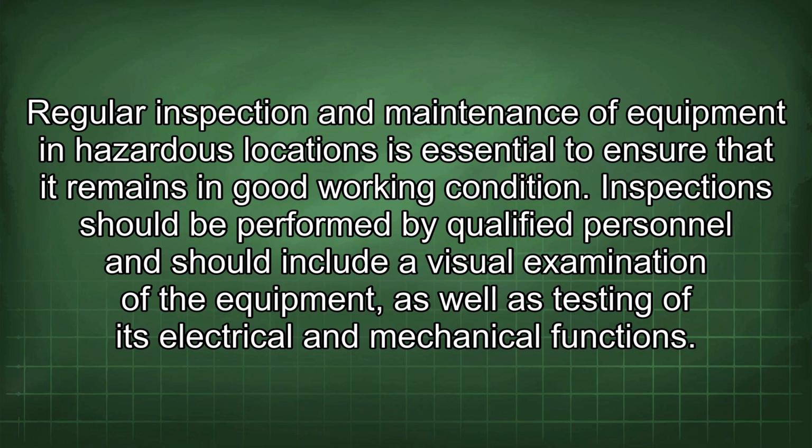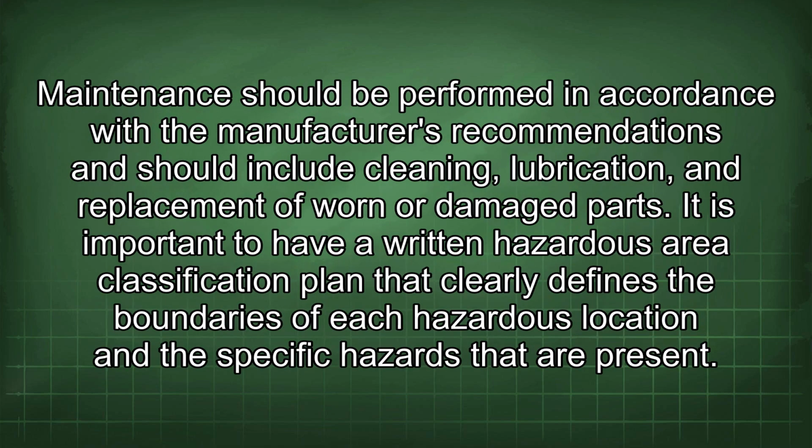Regular inspection and maintenance of equipment in hazardous locations is essential to ensure that it remains in good working condition. Inspections should be performed by qualified personnel and should include a visual examination of the equipment, as well as testing of its electrical and mechanical functions. Maintenance should be performed in accordance with the manufacturer's recommendations and should include cleaning, lubrication, and replacement of worn or damaged parts.